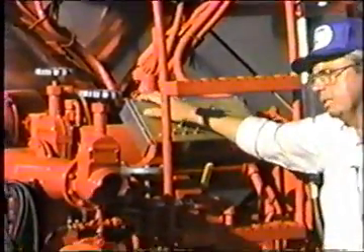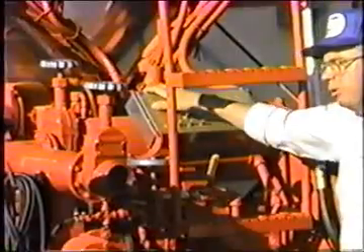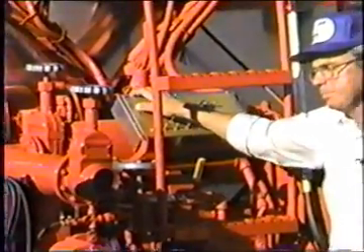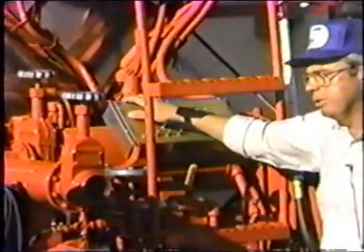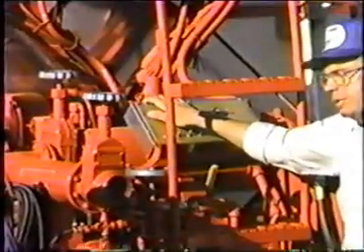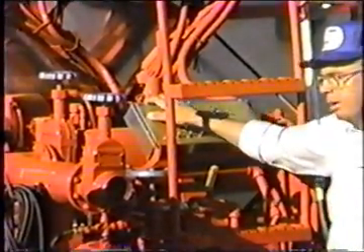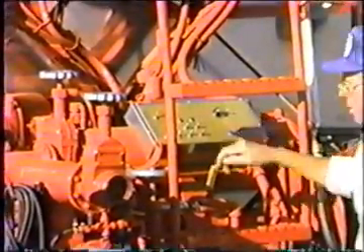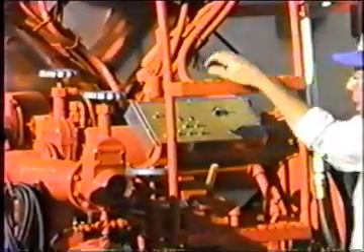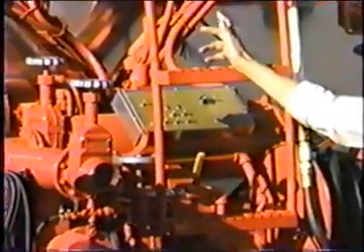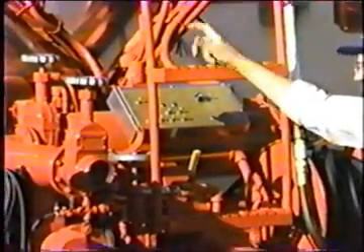All the rest of the time, you're going to leave this rear master in the on position. This rear master is in series with the front master. That is, they both have to be on for anything to turn on. If you put this off and then go to the cab of the truck and try to turn the bar on, it won't turn on.